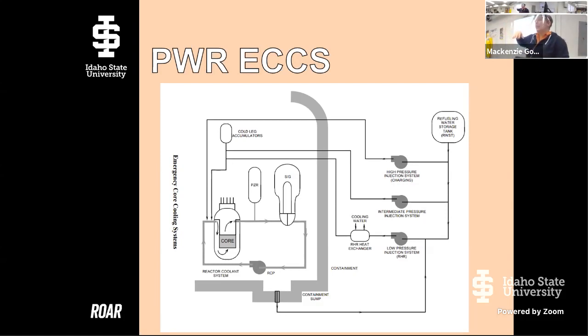When we talk about BWRs in a second, you've got steam in there, and as you put that in, it's going to immediately condense that steam back into cold water, and you're going to have some big pressure changes. So typically, there is actually some heating in the backup water, but it just depends, right?